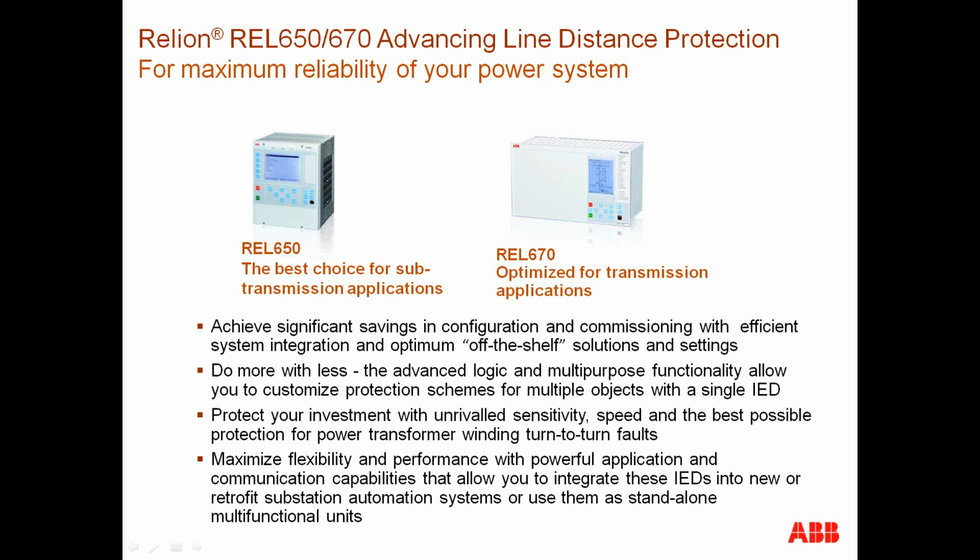And if you receive a signal from the remote end, a permission to trip, and you can't sense a forward fault, the only thing you have left to sense is, do I have a low voltage? Okay, because I can certainly have a low voltage there with a very weak source. Because if I have a fault on the line, it's going to keep that voltage down.